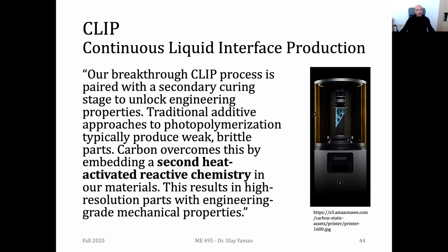Now we have a different version. Do you have a question, Adilcan? Hocam, is the part fully cured after the process, or does it need more curing after it? Yes, we need to do post-curing. The ones I have right here are not post-cured, and you obviously cannot feel it, but they are still sticky since we haven't done any post-curing operation. But once you do post-curing, their strength will be improved, and you have no uncured resin around. So again, as in the case of SLA, we need to do some washing and post-curing processes.